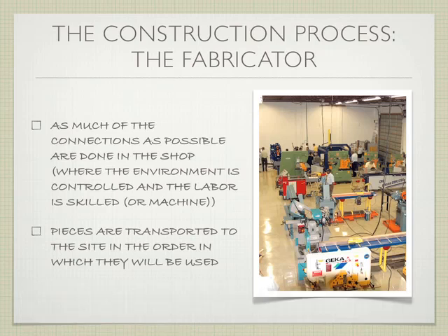As many of the connections as possible, right, are going to be done in the shop itself, right? Especially if they involve welds, right? Bolts are relatively easy to do on site, but if you're going to do any welding, you really want to make sure they're done in a shop environment. Why might that be the case? Ideas? Exactly. It's a controlled environment. Controlled temperature, controlled humidity, right? Controlled, basic, is it raining on me, that kind of stuff.